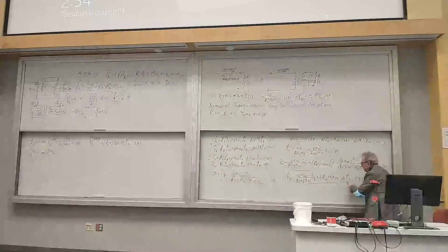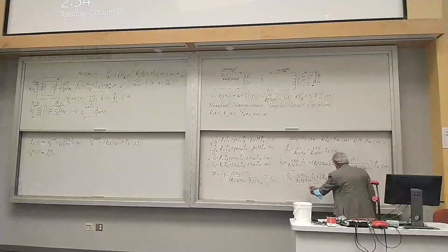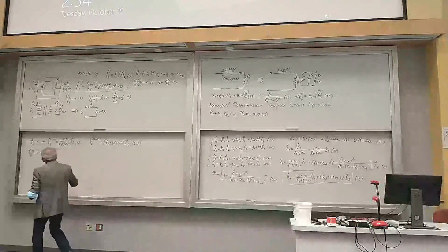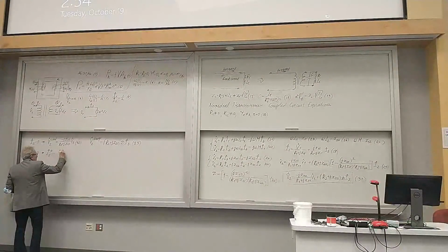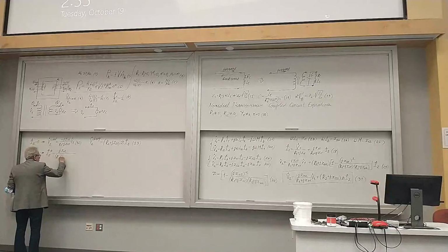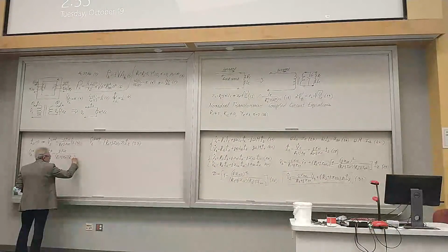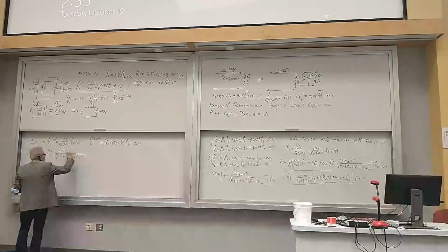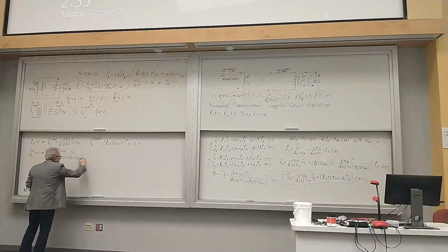Current, this will be short circuit current. So what I will do, I will move this term over there, this 0, and divide by this, and I will find this short circuit current. So when I move it over there, it will be j x sub 1,2, divided by R sub 1 plus j x sub 1,1, multiplied by R2 plus j x sub 2,2 times d, and times V sub 1. So this will be the short circuit current.